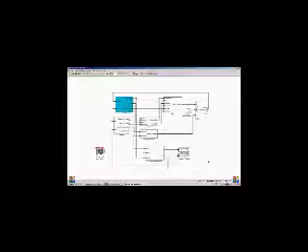Now let's look at another demonstration. This second experiment is a state-coupled 2-tank system which contains a pump to retrieve water from a basin at the bottom of the apparatus and feed it into the upper tank. The upper tank loses this water through a small orifice at its bottom, which feeds into the top of the lower tank. Using 3-term controllers, we are able to regulate the water level in the lower tank.